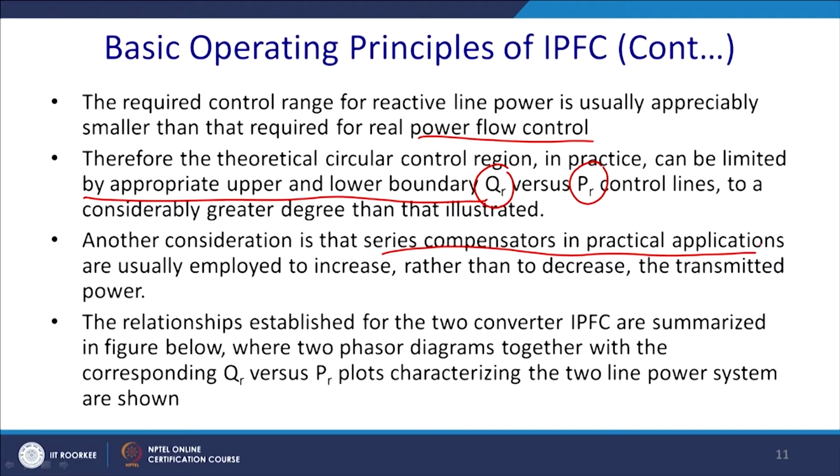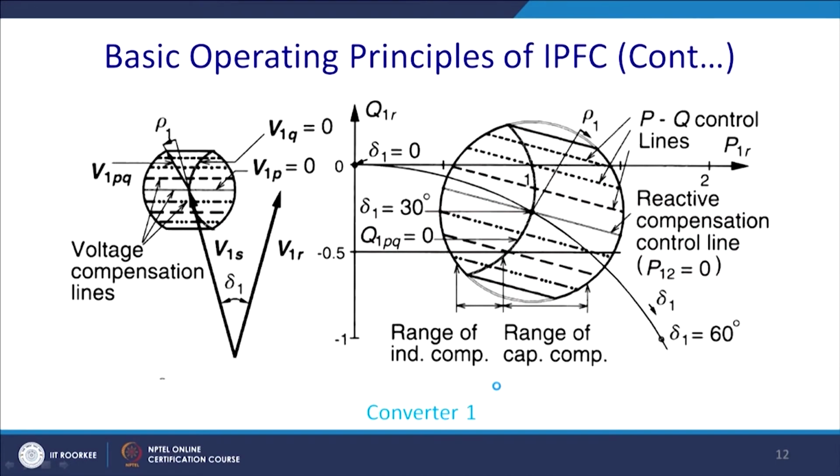The relationships established for the two converters of the IPFC are summarized in the figure on the next slide, where two phasor diagrams together with the corresponding sending end real and reactive power, that is QR versus PR plot, characterizing the two-line power system will be shown. So, this is the case where both 1 and 2 have been merged.